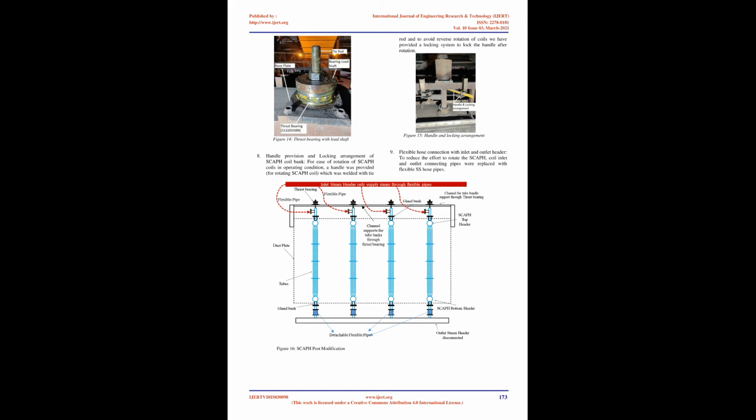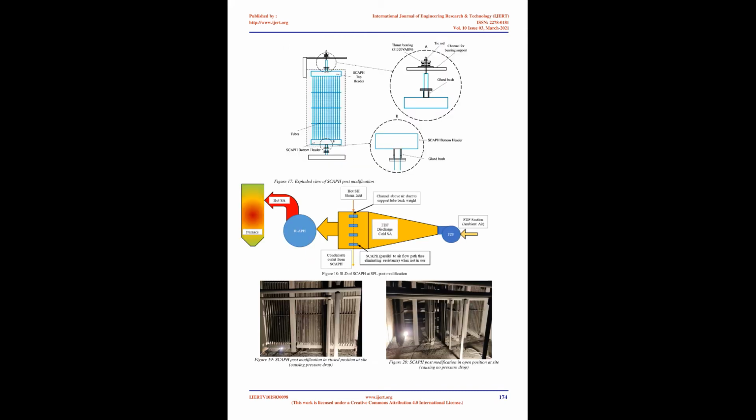At the top of the 4,200 mm wide duct of the forced draft fan, a channel of length 4,500 mm was taken, and to support the channel from the side, the same dimension channel was used, of size 600 mm, which was welded with the horizontal channel and at the side of the duct to provide proper strengthening of the channel.